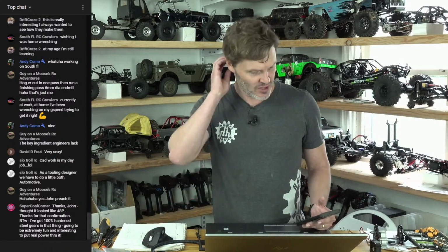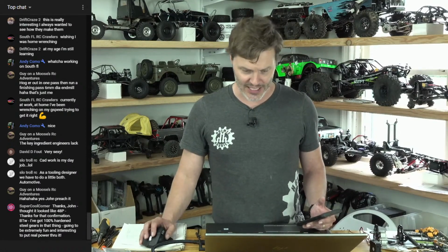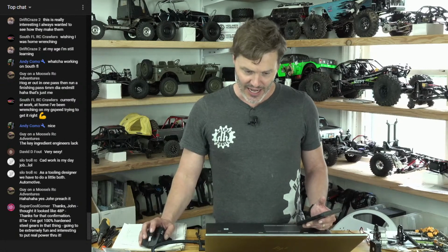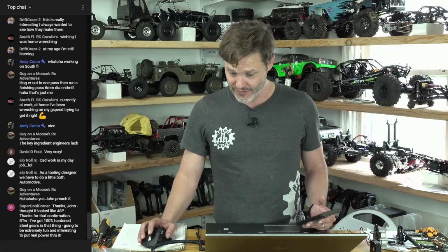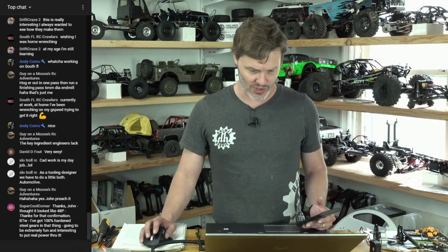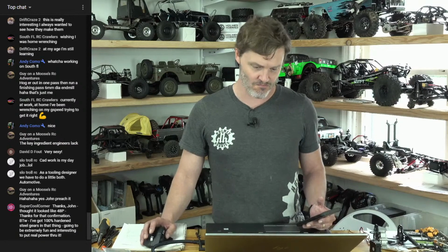That is a good point. Maybe I could just specify something with a little bit less radius on the side. I kind of like the way this looks, though. They could use a 0.5 millimeter radius, 10 millimeter for all that mattered, I guess, for this, as long as that radius fits in there. We got 4.72 radius on there, so it's going to have to be less than a 9 millimeter cutter to fit. 8 millimeter with a 0.5 mil radius on the nose, or a 0.5 mil radius on the cutting edge would work. Yeah, machinist talk. I love it.